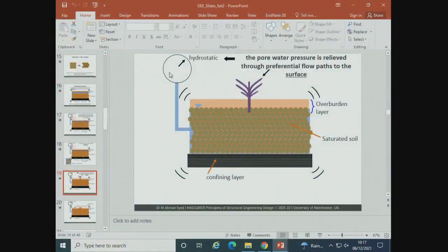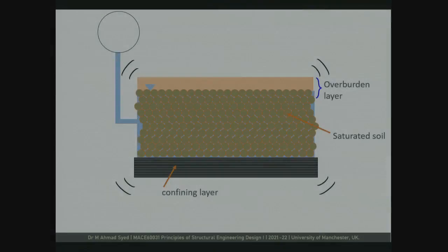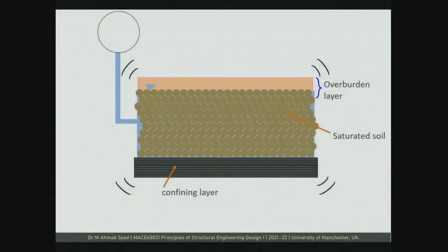So this pore water pressure, which is very high, will start to dissipate, but during the process of dissipation, there will be an upward flow of water. The water will tend to follow some preferential paths, and as I have explained, it can only come to the surface. During the process of this pore water pressure coming to the surface, it collects all the sand that comes in its way. Okay, because it is pressurized, it digs some sand and dumps it at the surface.